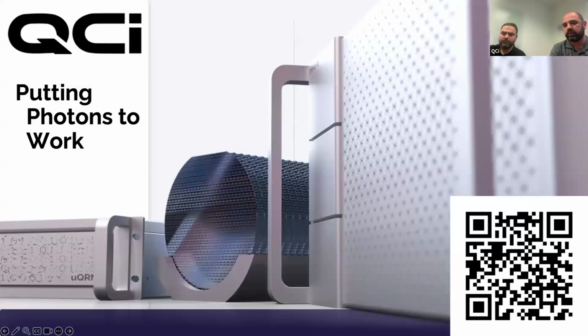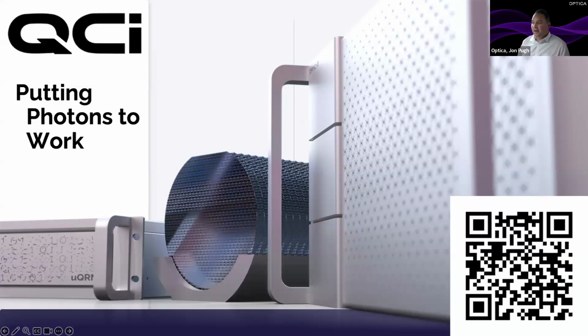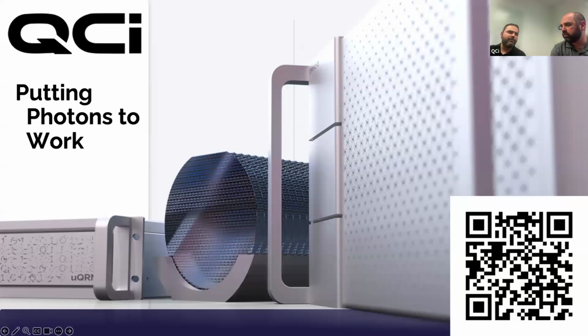Fantastic. And later on in your talk, you discussed the tunable filters. What's the theoretical limit with TFLN of how narrow the tunable filter can be, even if it's fixed? Yes, we can talk about the quality factor. I think the theoretical limit for the quality factor that we can get, which determines the resonance and the width, would be around a quality factor of 100 million, if I'm not mistaken.